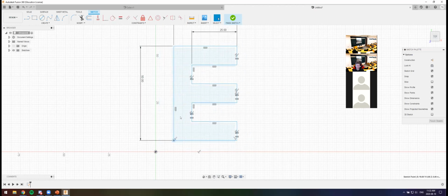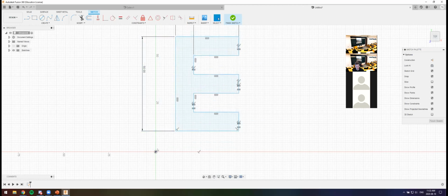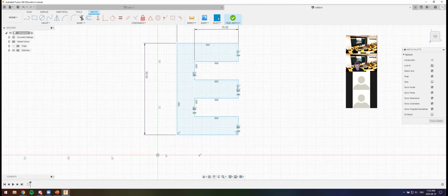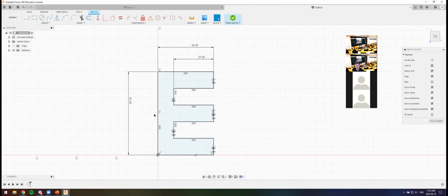All right. If I want this to be rooted, what I want to do is grab, okay guys, again, this point right here, the one with the little nuclear symbol around it. This is called the origin. All right. So I'm going to click the coincident constraint, Jacob. This one here, and then I'm going to click the bottom left corner of my E and the origin, and they will snap in place and live happily ever after.